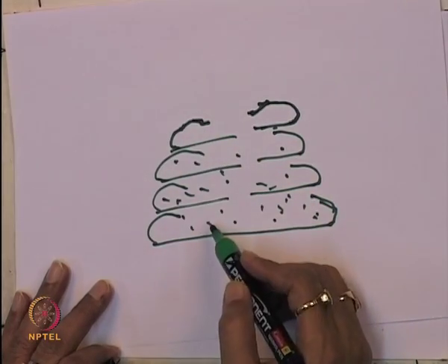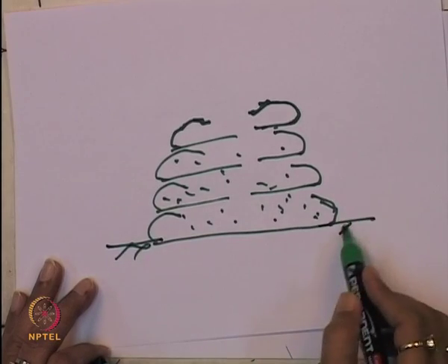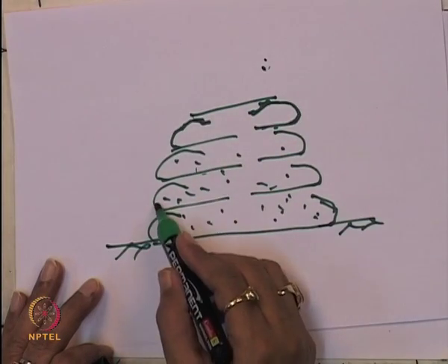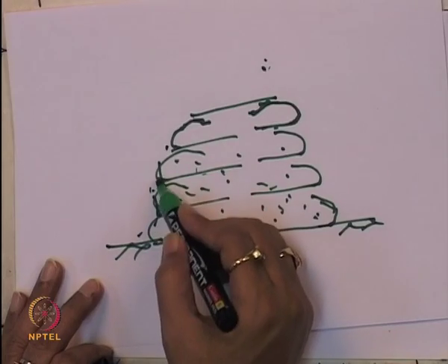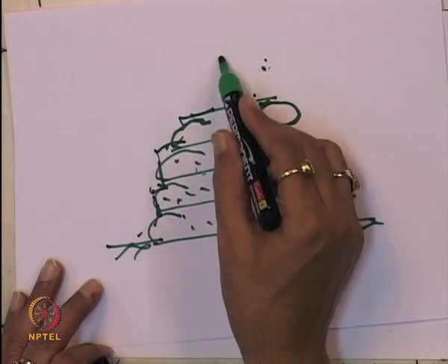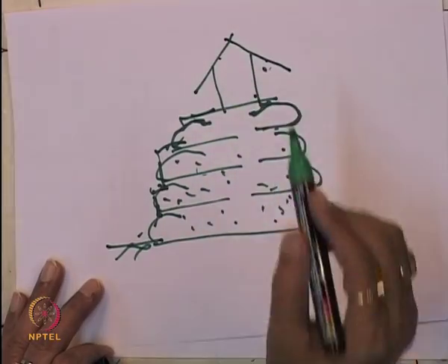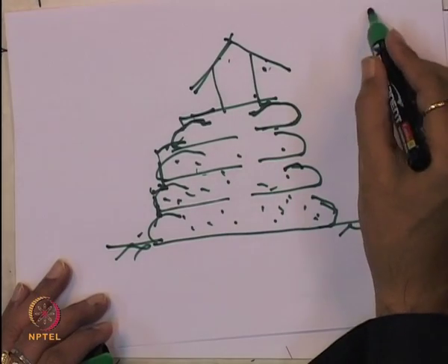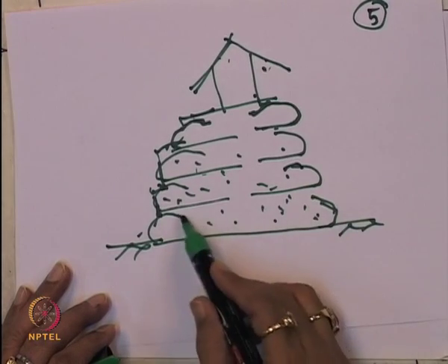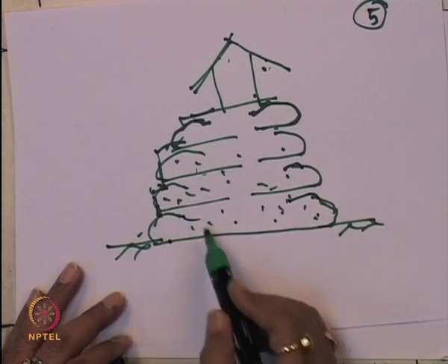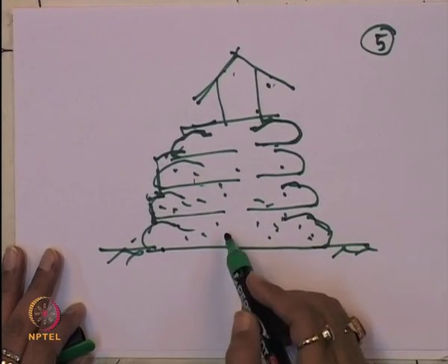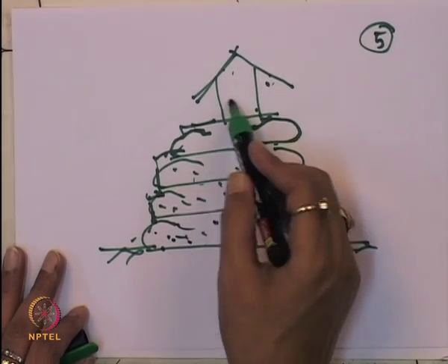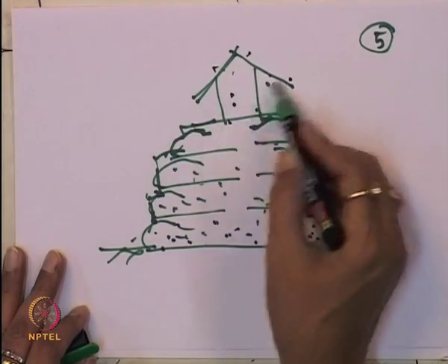of wall. This also we will study. So near the seashore you can construct a wall like this, and people can go up very fast to the top of this, and you can make a temporary shelter there, a house, to protect themselves. Most important is how you can protect the people. You can easily construct this; this is geosynthetic material, a flexible material, which may be woven and non-woven geotextile, and you can fill it with local sand near the seashore and construct this wall, and on the top you can make a house or shelter.